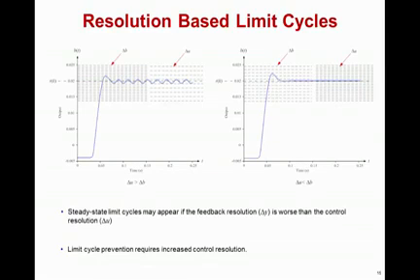Let's go through some limitations that occur when you try to put this equation into a processor. The first talks about the resolution of your analog to digital converter versus the resolution of your PWM output. The delta B shown in the graph is the amount of change from your analog to digital converter. This means there are this many steps shown in the graph that the ADC can accurately measure. In other words, the closer the lines are together, the higher the resolution.